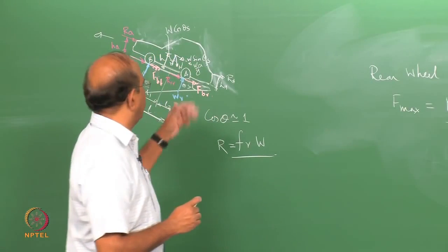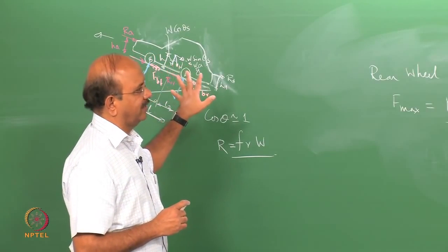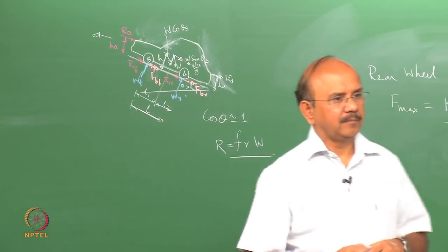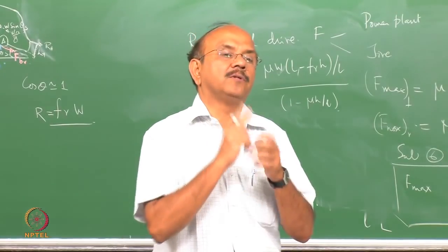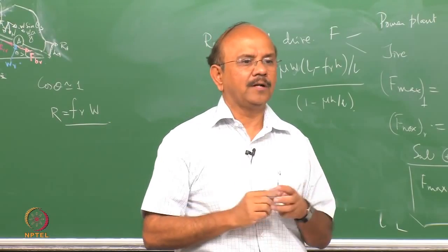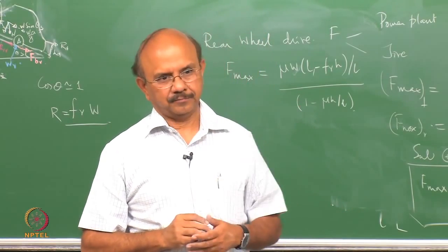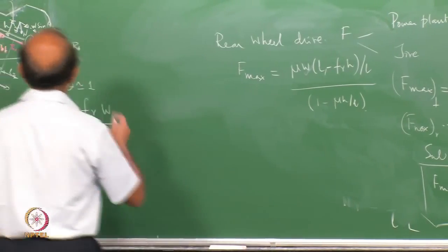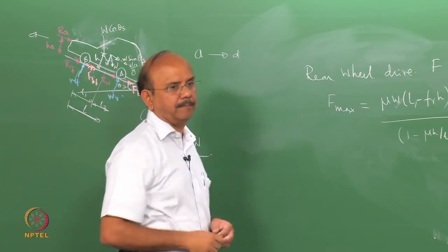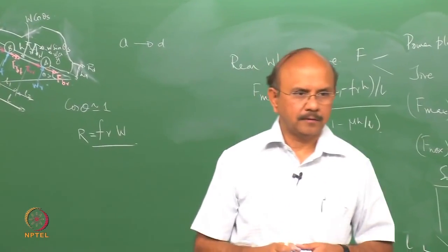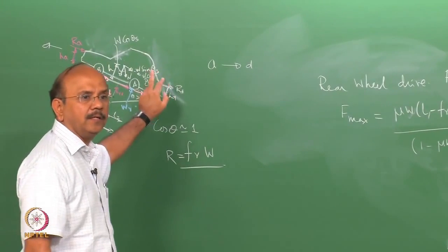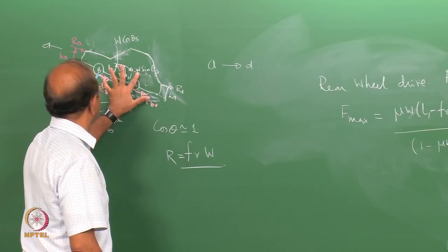Though it's not theoretically very correct, I should have A and put it as minus A. Just for ease of understanding, every time you look at A, you have to say that actually I am at minus A when I am braking, plus A when I am accelerating. I will replace A, or minus A, by D, where D is nothing but deceleration. That makes my job much simpler. So when I am decelerating, what happens to my D'Alembert's force? It will switch.